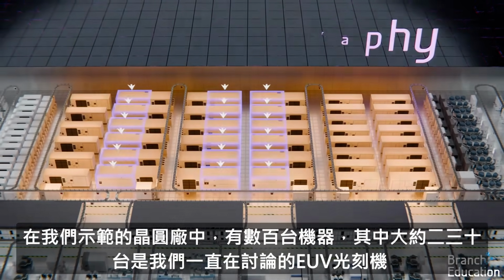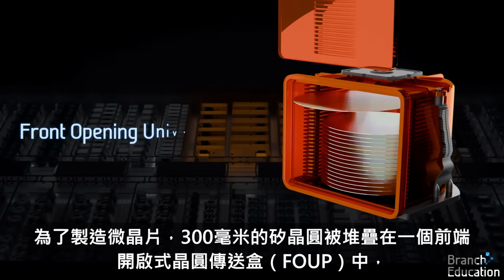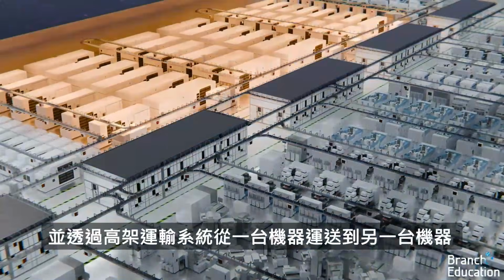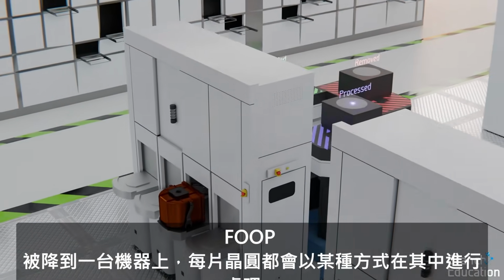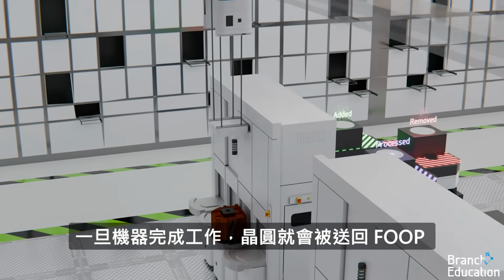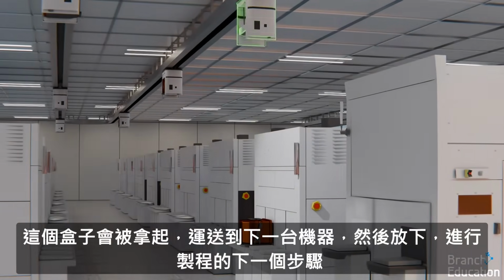we've been discussing. To make a microchip, 300mm silicon wafers are stacked inside a front-opening universal pod, or FOUP, and carried from machine to machine using an overhead transport system. The FOUP is lowered onto a machine where each wafer is processed in one way or another, and once the machine completes its work, the wafers are returned to the FOUP. The pod is picked up, carried to the next machine, and dropped off for the next step in the process.